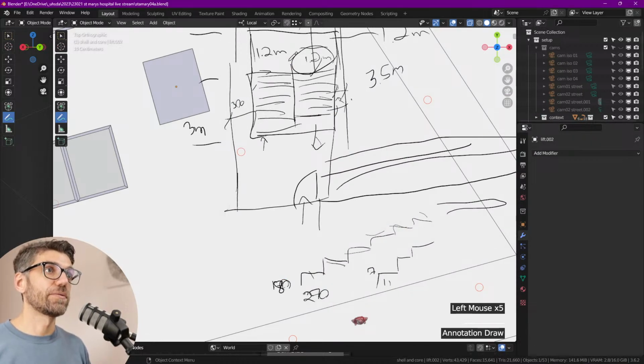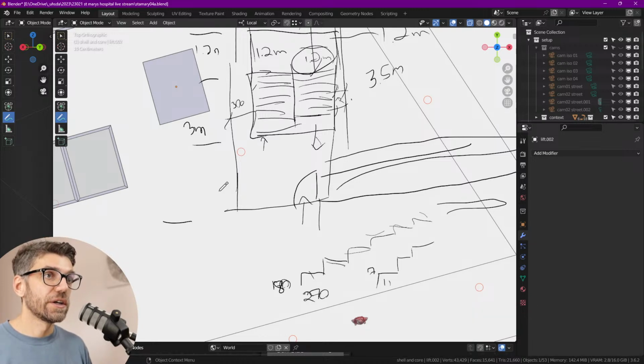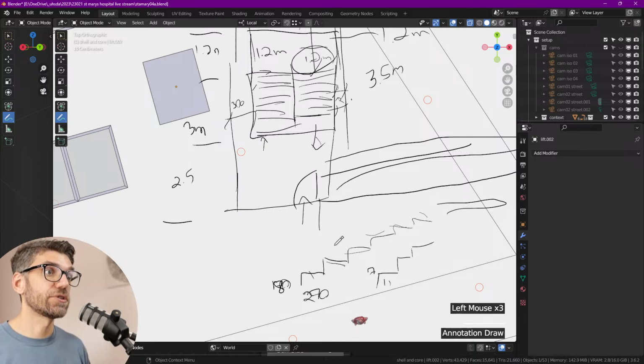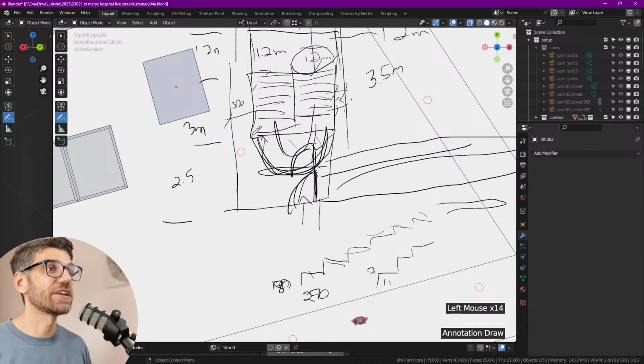And then we've got, what do we say here? 1.2 meters. Wherever we have the exit, that needs to be a bit more generous, so that should probably be like 2.5. Why does it need to be more generous? On the upper floors, that door opens on the inside. Man, this is getting technical. When people are going down, if that door opens over here, then it's encroaching on the clear space. That clear space has to stay clear. Usually in buildings, it gets drawn as a little line for people to understand exactly what's happening.